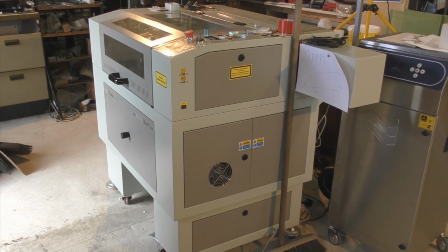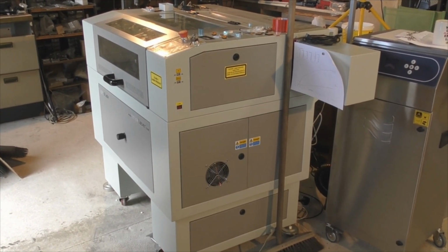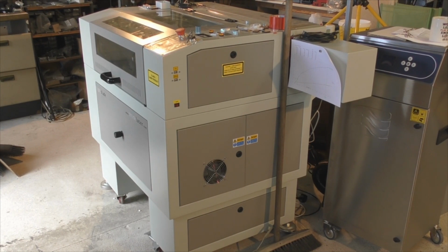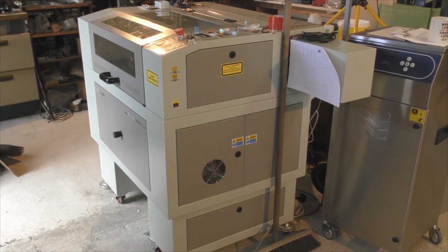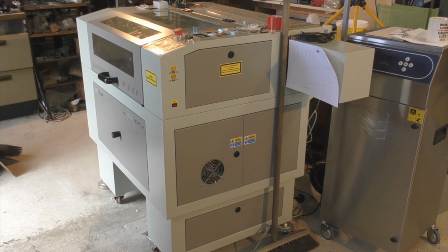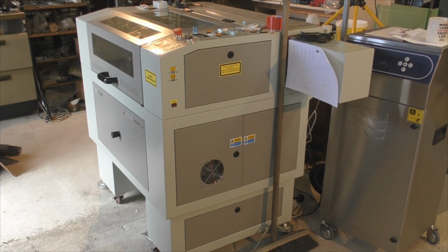On this machine here, which is the light blade machine, we have something called a servo. To be honest, it's not a servo. The motors that are on that machine are still stepper motors. It's a stepper motor driven system, but the steppers have got a special addition to them. On the end of the shaft, they have what they call a rotary encoder.